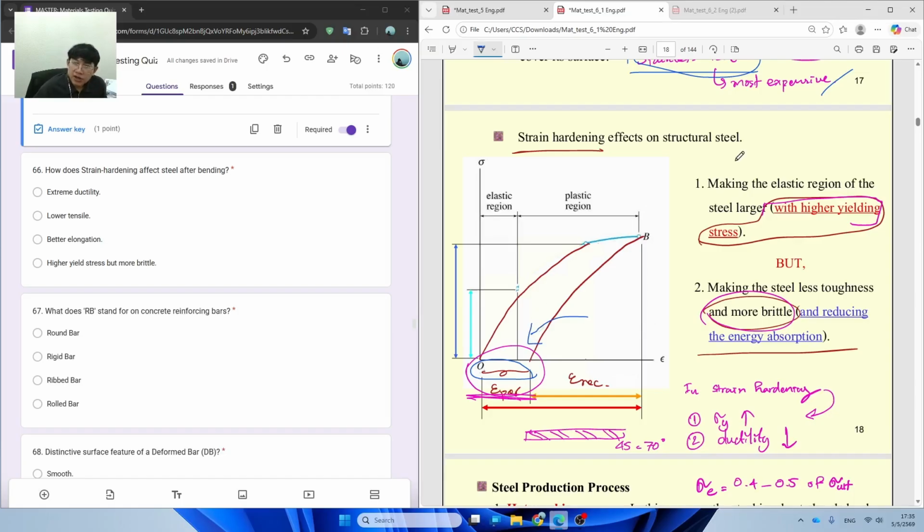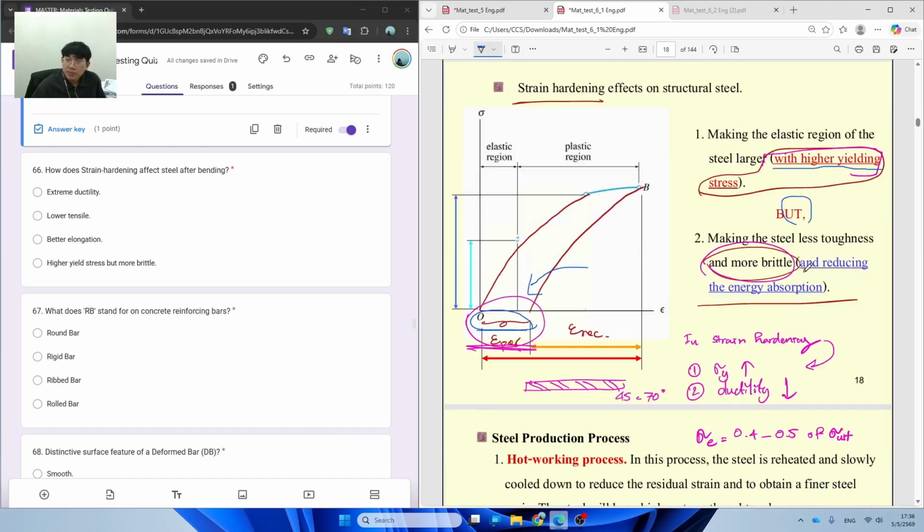And that material is going to have two remarkable points that we need to always think about. It's going to have a really higher yielding strength compared to the hot rolled steel, but according to its property that it produces the permanent strain, it has lower ductility compared to the hot rolled steel.